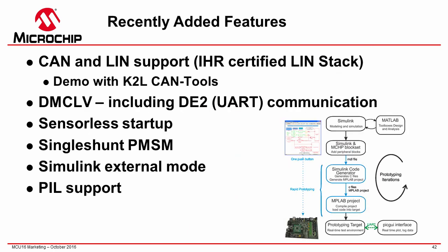Recently, we have added CAN and LIN support. We are using the certified IHR LIN stack, and together with the K2L analyzer tools, you can have a nice automotive bus system solution. We are also supporting the DMCLV demo board and the included DE2 communication, which is an additional UART communication with the MOSFET driver.